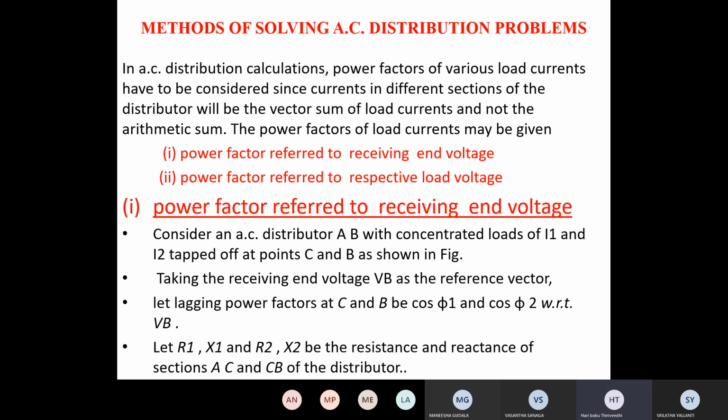Switching equipment requirement is less for radial type, because not many equipments are used in the radial type, but it is very high for loop type. Why? Because every section of the loop has its own sub feeders also. That's why we have to provide switching equipment, I mean protection devices.